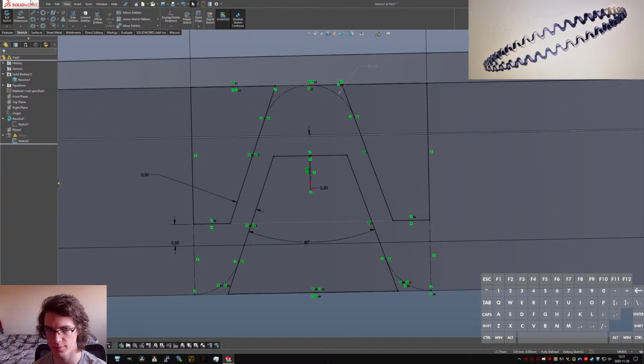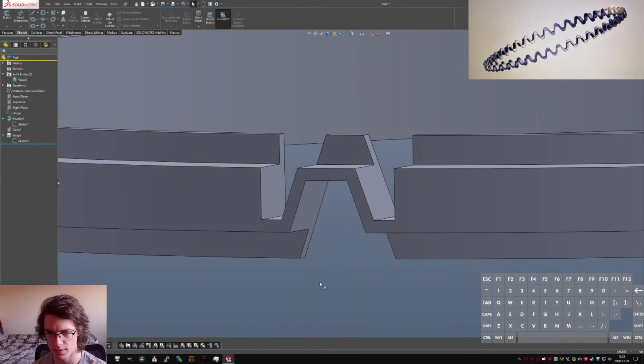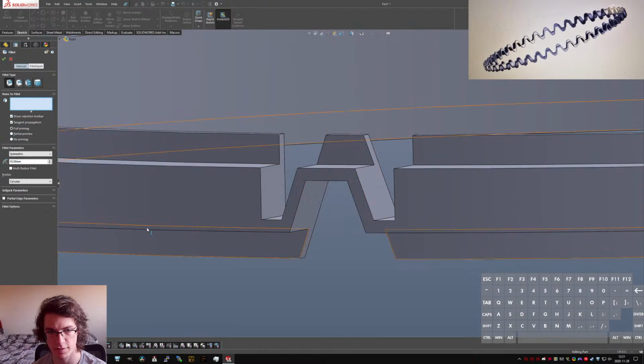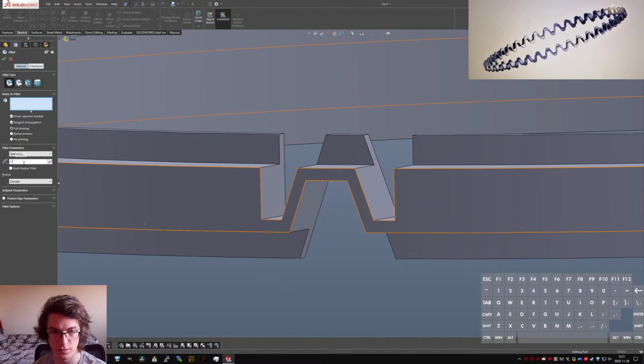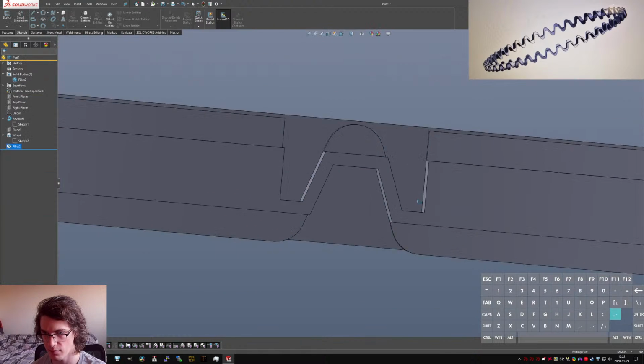So now I've got three solid embossing features that'll work, and then I can do a fillet. Oops, I'm at face fillet. I can make this guy equal to radius at sketch 2. And when I come up here, now we have radii.